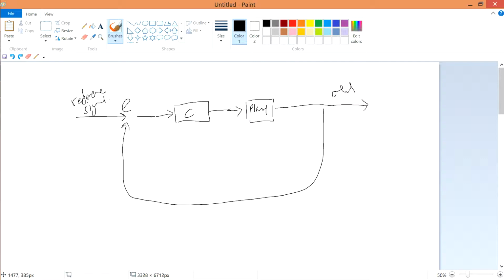So the more controllers you have, or the more blocks in the block diagram, the higher degrees of freedom you have. Therefore, instead of the filter, we still deal with the controller, so I change the controller to a PID controller. This PID controller is somewhat like a second order system, right? Two degrees of freedom of a system to control your plant.